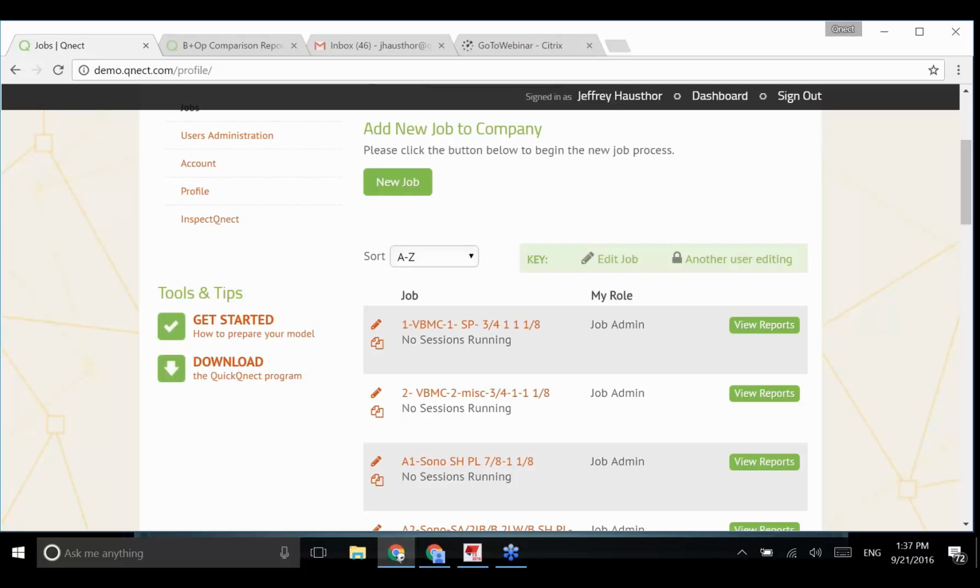All right. And then the weld sizes? Oh yeah, of course, we iterate. We do full limit states on all of that in the AISC. So we always start with the minimum thickness required for every weld and iterate up slowly until we match the limit states for all the welds that are in there.